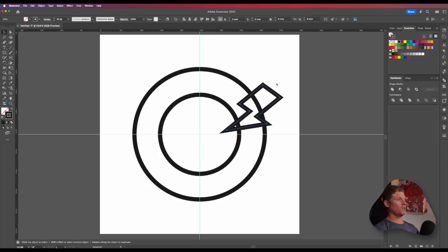So the easiest way to do that is we're going to click and drag, and we're going to get a reflect tool. So you can hit O, or you can go over here and you can see this is reflect. Now you can see there's a tiny little node over there in a very light cyan color that you can barely see. I gotta get my eyes tested. So I'm going to drag this to my horizontal line over here. So you see I've just put that little center point on this line over here.